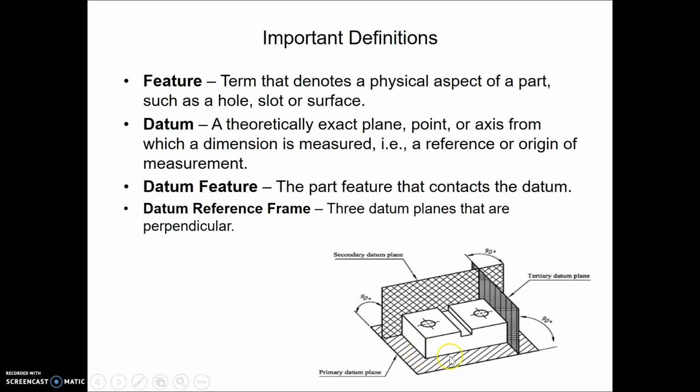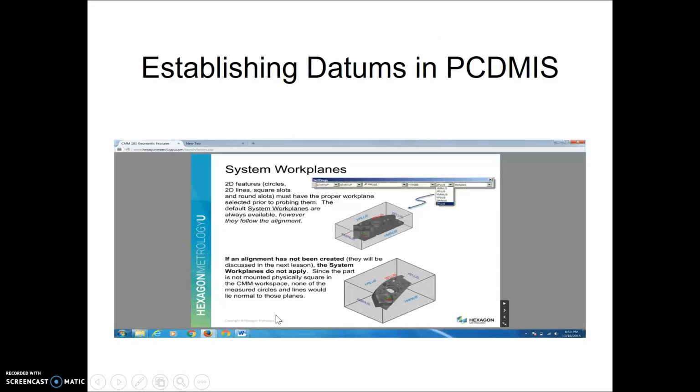So for instance, if we were holding a physical part and using it as a master, and let's say the left plane was to act as the datum, the left plane on the actual part itself would reference the datum feature. We also have datum simulators, and one important and critical datum simulator would be the surface plate. We'll look at that in just a moment.